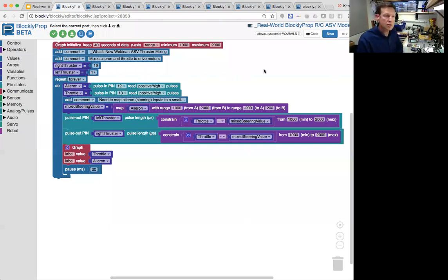Okay, so what you're looking at is just a piece of code which receives the pulses from the throttle and the aileron, or radio, on 2 I/O pins. People always wonder how things like this work, but it's all really, really simple if you just research it. You get these 2 pulses, and then I provide a mixing value, because what I want to do is provide throttle on the left, and then the right can just be steering. So I map the aileron value to a new range, -200 and +200. Then I mix it in with the throttle so I could steer this thing.